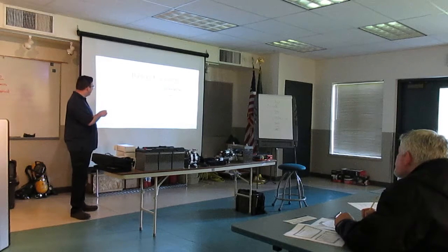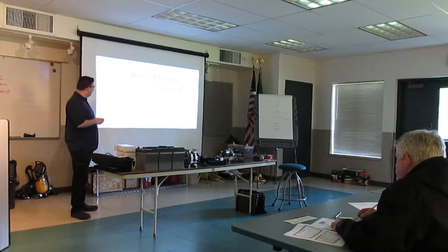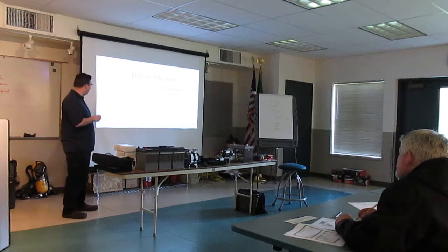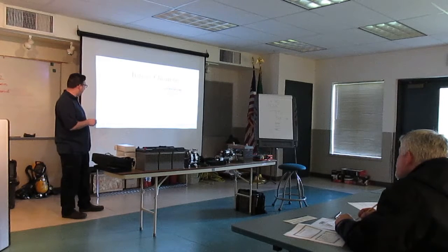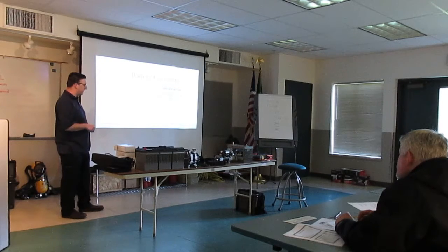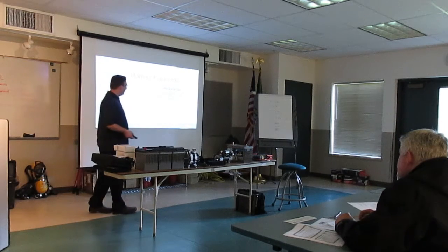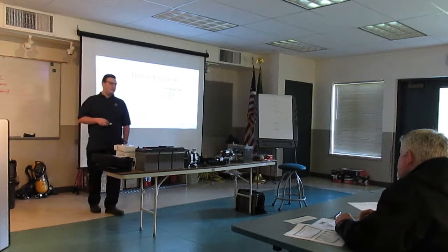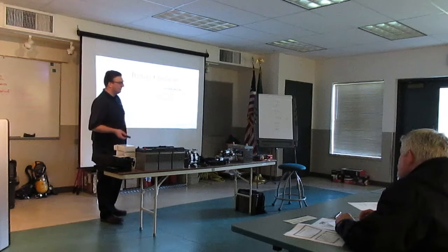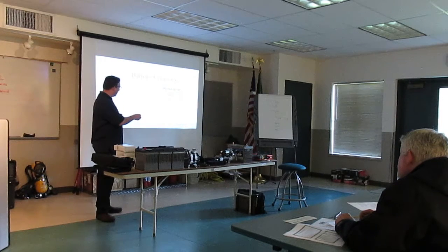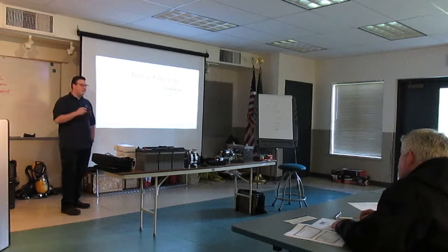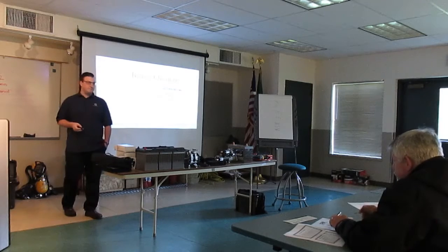For our battery chemistry, standard lead antimony, 2.35 volts per cell, 14.1. Maintenance free, 14.7. Most AGM, 14.7 to 15 volts. These are our charging voltages that we're dealing with. On certain alternators, you will see set points on the regulators. The set points on the back of the regulators are adjustable. The set point is based on battery type, because different battery chemistries like a little bit of a different charge for each one as they're going through.